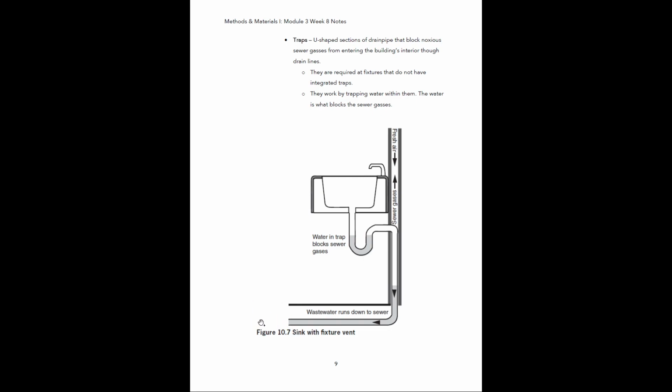So the purpose of the water that's trapped here in this trap is, when that gas from the sewer lines wants to work its way back up through the system and come up here, it's going to hit the water right here, and this water is going to block it. So this is basically acting as a gate that is going to be preventing the gases from entering through here. Or I guess a better term would be a wall. So this is just blocking off access for these gases, making their way back up through your sink and into the air where you can breathe it. All right.